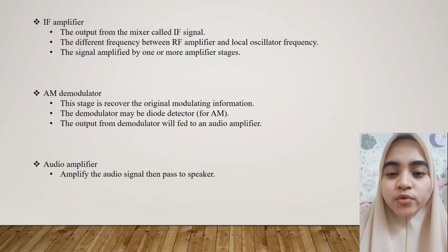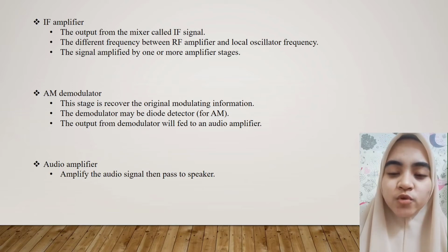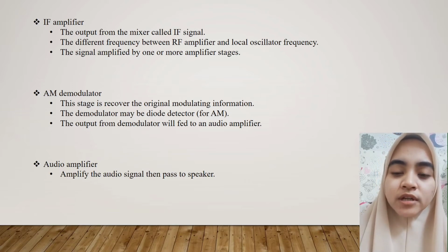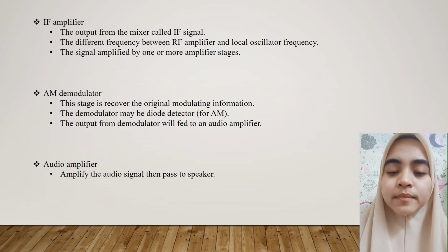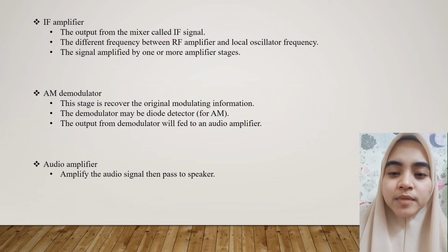Then we have demodulator. This stage recovers the original modulating information. The demodulator may be diode detector for AM. The output from demodulator will feed to the audio amplifier. Last component is audio amplifier. It amplifies the audio signal then passes it to the speaker.